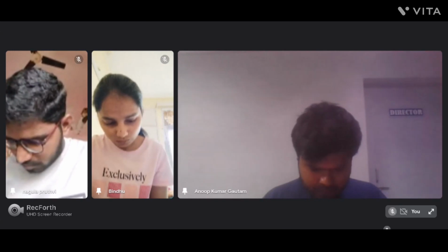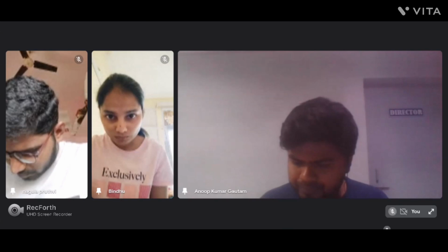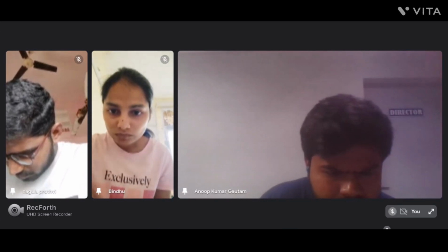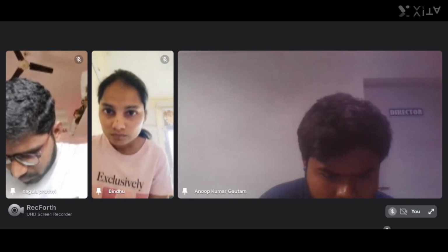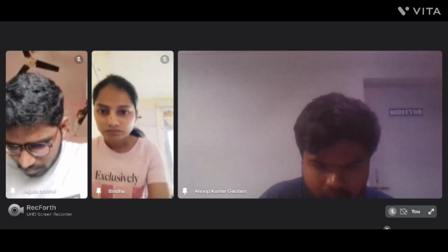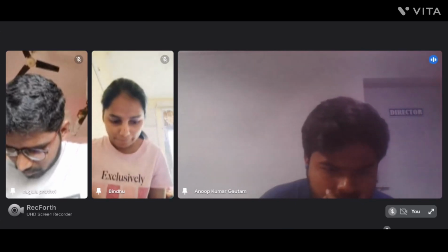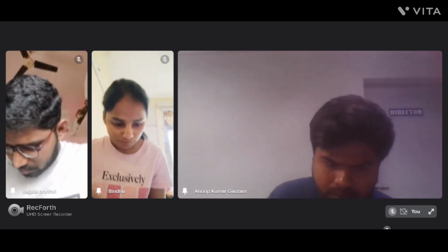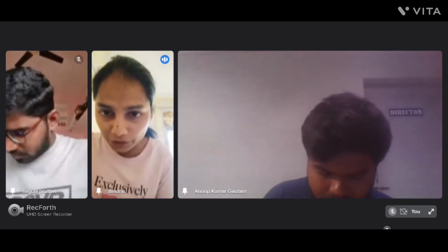Hello, Raghavendra. So other people, I want you to just do this question. Second question: always @ begin, then Q1 is equal to A, then Q2 is equal to Q1, where A is assigned to Q1 and Q1 is assigned to Q2, then end. I want you to draw the hardware diagram of that module. Raghavendra, Gopika, Bindu, and Amit, did you get it?